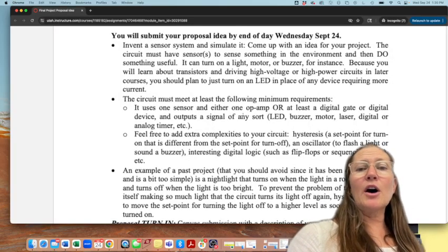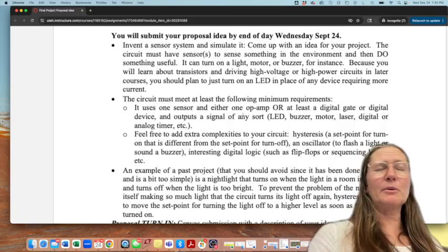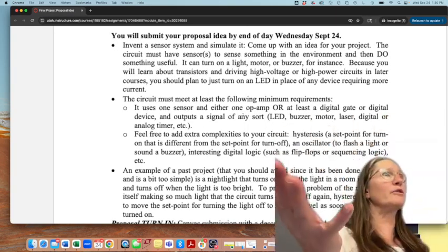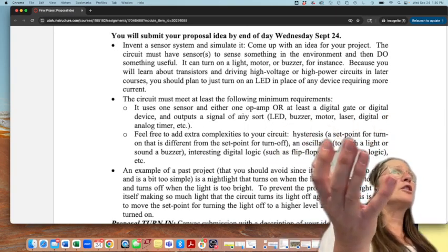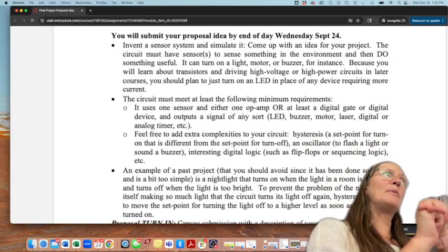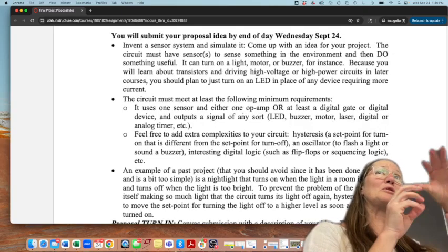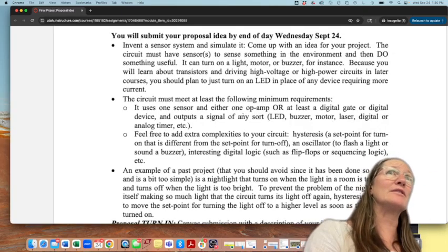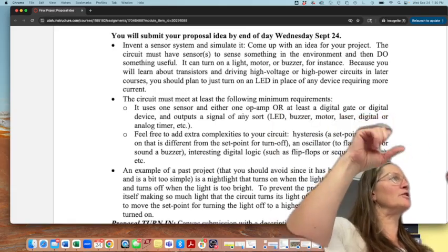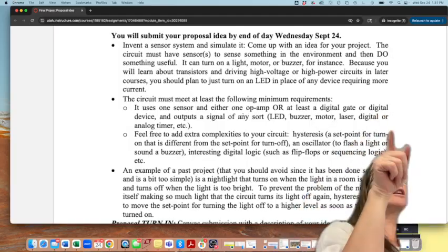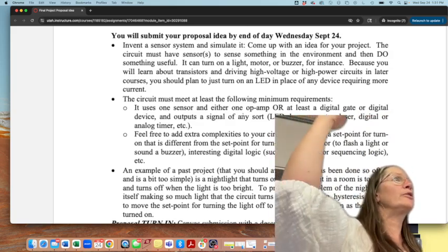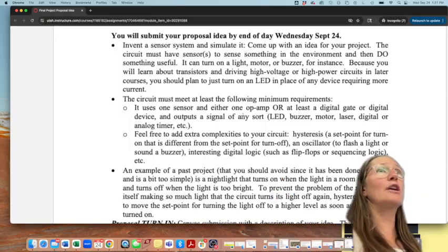Then the op-amp or comparator, the comparator or the digital logic. So when you're doing that, we talked about how you convert that into digital logic. Those sensors are usually going to be read through voltage dividers, which are the easiest system to set up. And if you take measurements between two different locations, one a reference and then one of that, you can get a wider range of values to give you more of a high and a low value. So that would be a way to get it into digital logic.